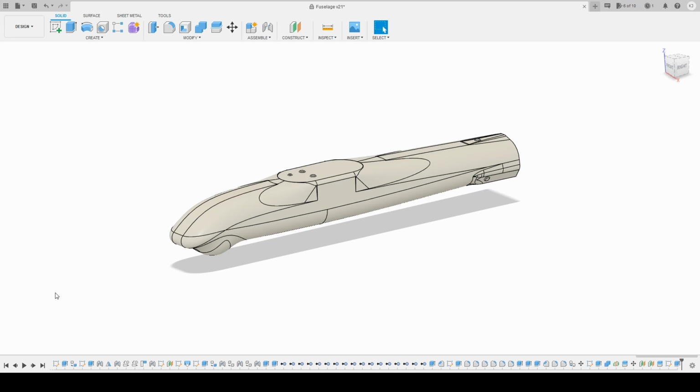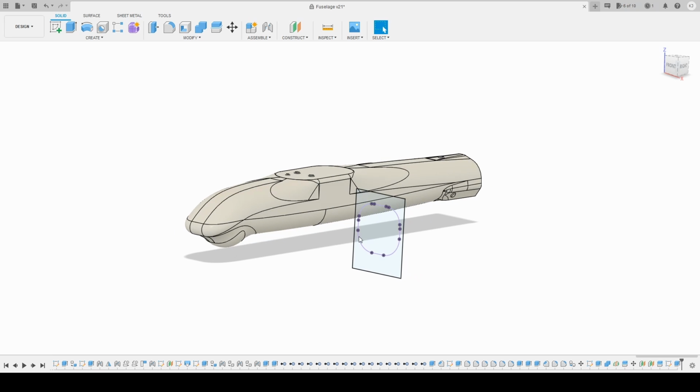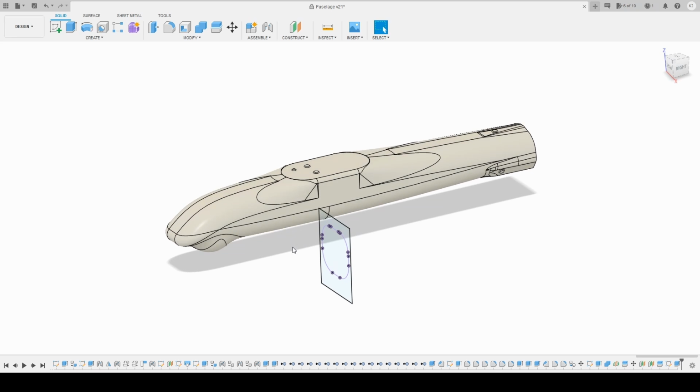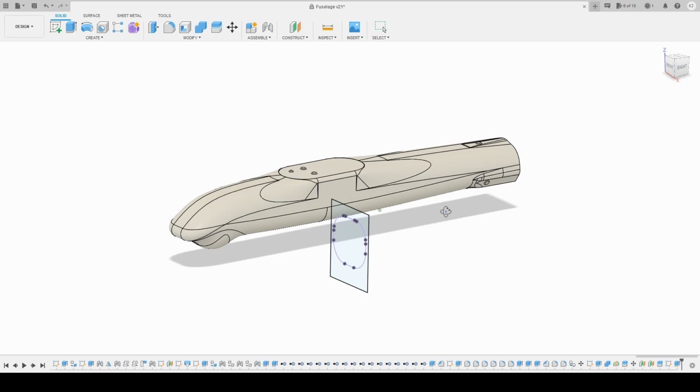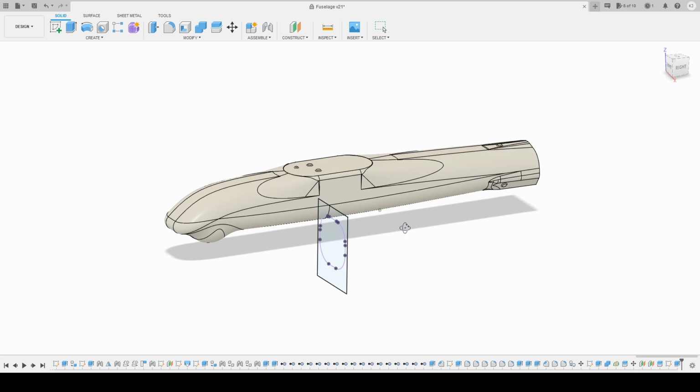Something you could do to get it started piece by piece is you could put planes into the CAD geometry and then get the intersection, and here you have a nice contour that you can use. But then you have to generate 20, 40, 50 of these to get the actual cross sections that you use to cut the shape with your wire cutter.